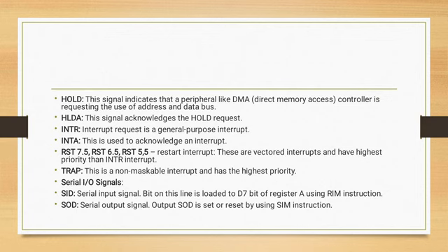The microprocessor acknowledges the interrupt signal and issues the INTA signal after receiving the INTR request. So INTR is enabled or disabled by software. An interrupt is used by an IO device to transfer data to the microprocessor without wasting any time.